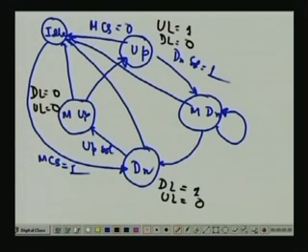Now one has to ensure somehow that the specification that you give for the system is that first the up solenoid is exercised and held till it goes to the up state, and then when it goes to the up state, the down solenoid is exercised. So this is the desirable cycle of the machine. Some device has to compute when to apply this up solenoid and when to apply this down solenoid, and it is the controller which is going to do that.